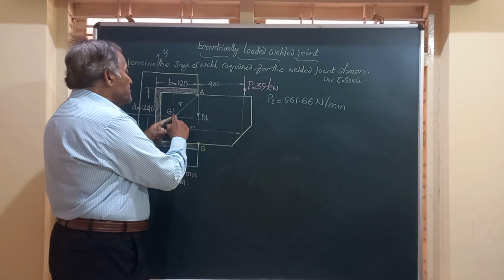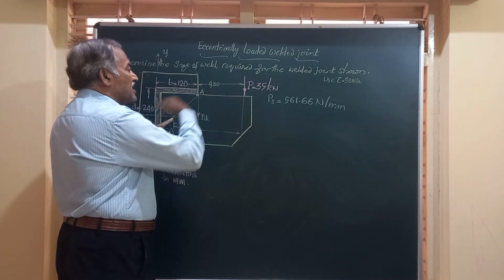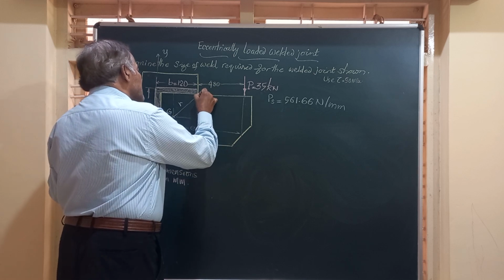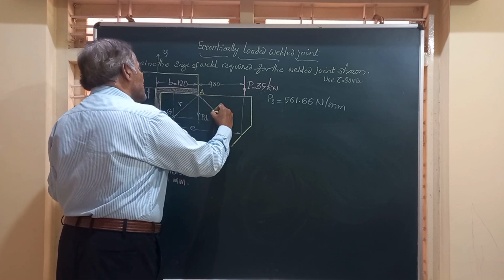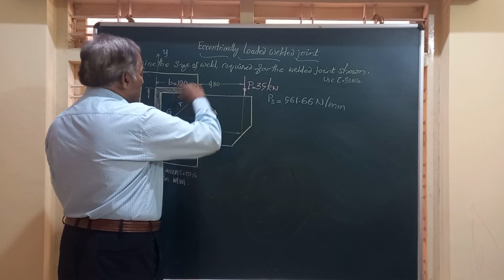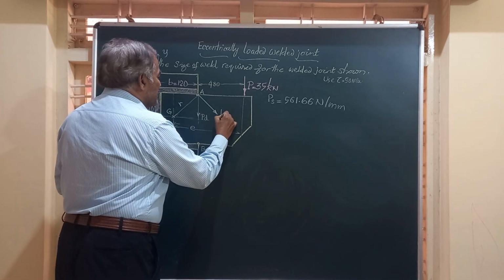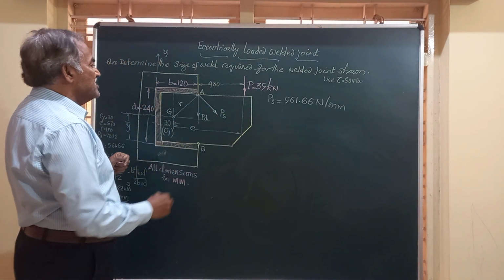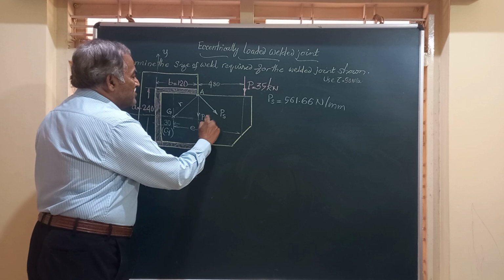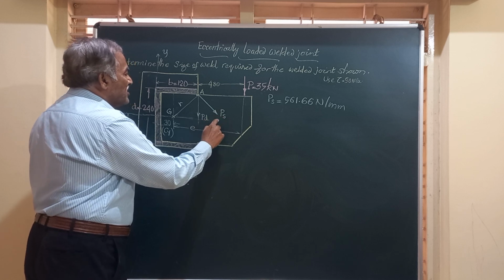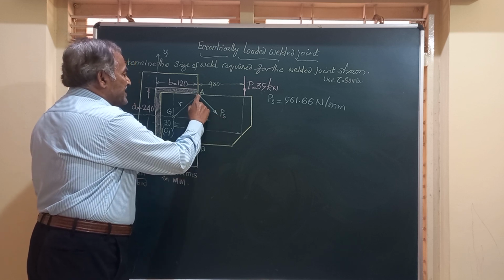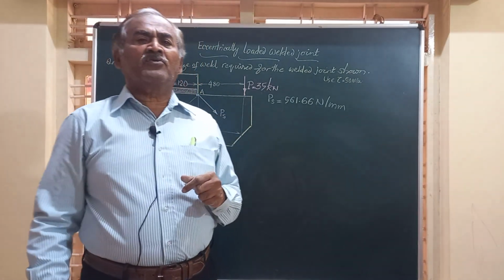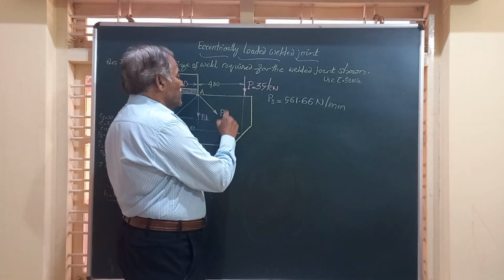Friends, about G, P is producing a clockwise moment. So also PS acting here perpendicular to that should produce a clockwise moment, and this I will call PS. We know the value. Friends, now PD is the direct load, PS is the secondary load, and it will be acting at this point A. And next comes the calculation of the resultant of these two loads.